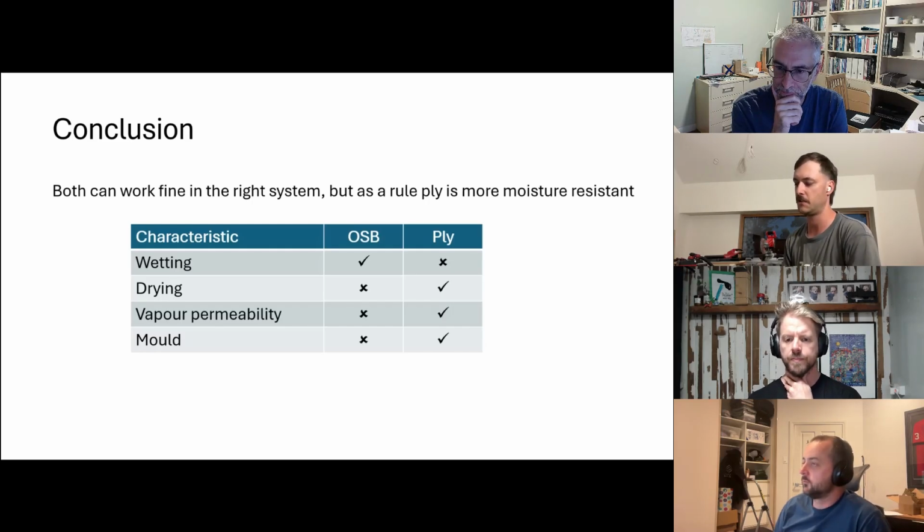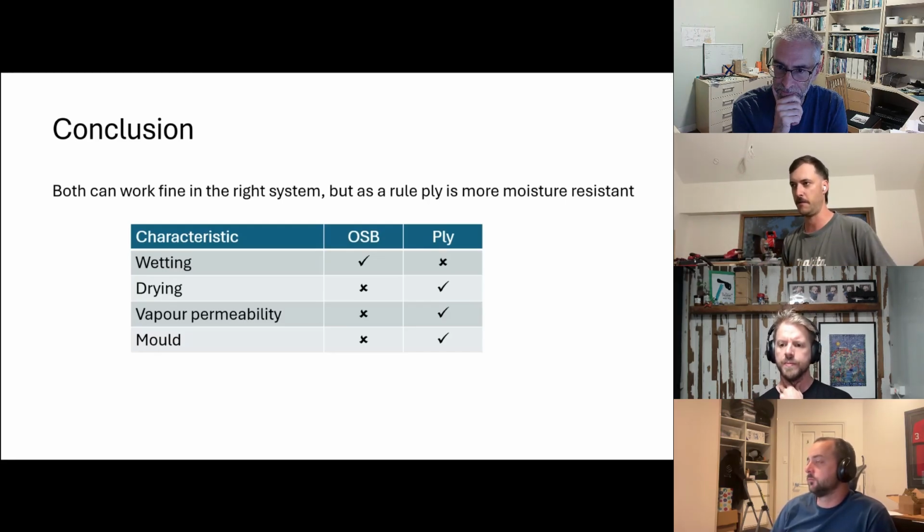Like, I drove past a site the other day in Launceston, and they had a steel portal frame. The whole house was steel. Then they just smashed ply over it, put a microporous membrane down, and had tiny little counterbattens. It's like, oh, we know that's going to be mouldy, but with the proper build-up, like Cam's saying, and that's kind of a question I had.